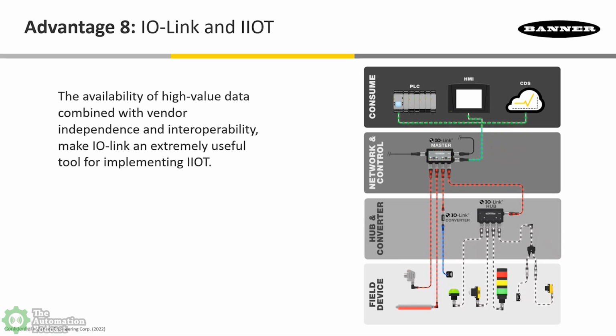Yeah, so our Snap Signal portfolio uses a very similar controller as what's shown in the IO-Link world, except it's based on an RS-485 protocol. With IO-Link, you have all these different devices that may be installed, or you may want to add to a machine to do condition monitoring. You can convert all of these to a unified serial protocol, like RS-485, and connect it to our DXMR90-X1 controller, which looks very similar to the IO-Link Master that we have. But it has some other advantages because of those Modbus RTU ports on that device. You could connect lots of different sensors.